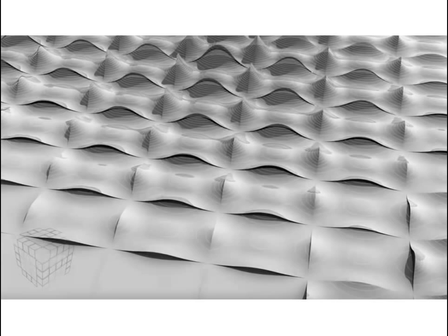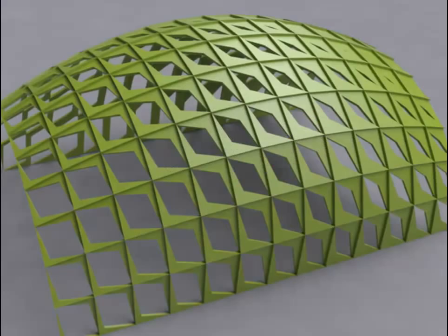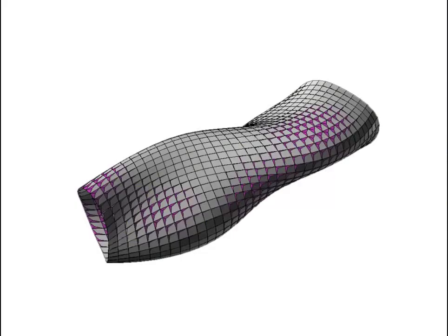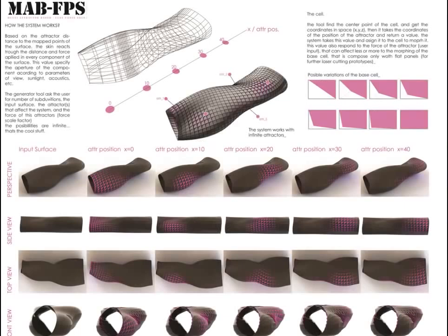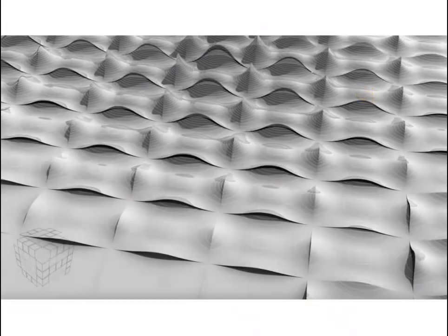So there are all different ways of taking an attractor, looking at the distance, and then, with a little bit of math, equating that distance to the distance between these 2 points on a surface, or the choice of whether to choose one of these tiles or the other. There's probably a threshold. So let's say if the distance is between 0 and 5, it's this tile. If it's between 5 and 10, it's this tile. You can set these up parametrically.